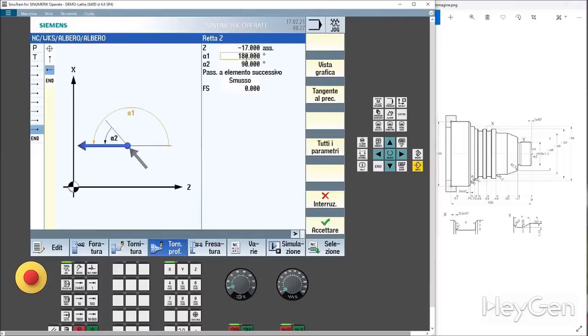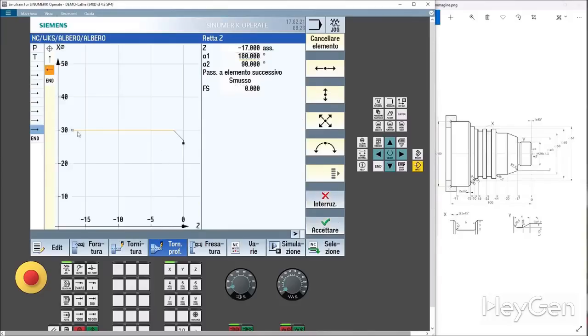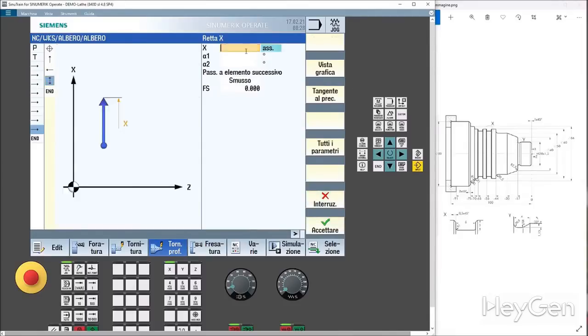It automatically takes me to 180 degrees because I didn't specify anything, and that's normal for the movement I requested. Chamfer 0, I don't put anything, so it will give me a sharp edge. Alright, I've arrived here. I'm moving to X40, so a vertical movement to X40.